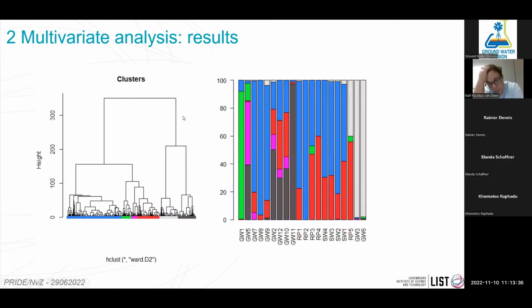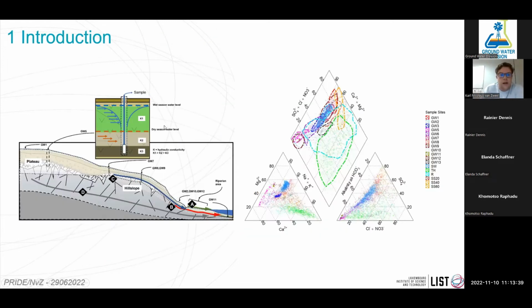So then what we did is, just to quickly go back, the problem is our wells intercept various flow lines, and you have a really high variance in vertical conductivity due to the soil being deposited there and not weathered. If the system is wet, you have really high lateral conductivity. And as it dries out, obviously the conductivity decreases. So if you were to sample in the wet season, you will more or less only be drawing in water from the shallower flow lines. And as the system dries out a bit, you start getting contributions from deeper flow lines, or you can see the signal at least.